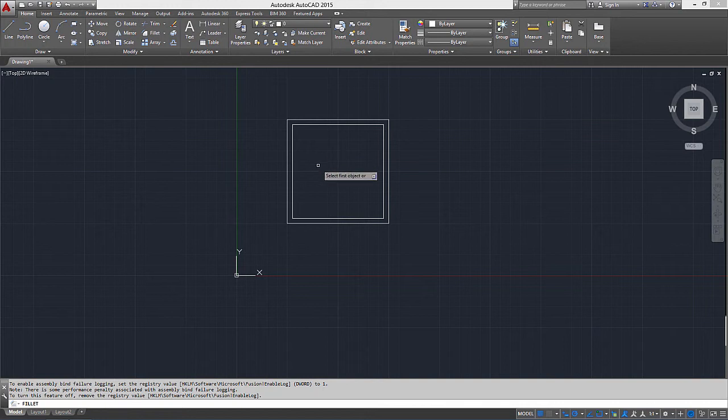So what we need to do is use our down arrow and tap down till we come to radius. So you can keep going around. So you undo polyline, radius, trim, and multiple. So we'll hit radius and then hit enter, and then we need to specify the radius value. And now in this instance it's 10 millimeters. And again, you have to keep hitting enter. And then we can select the first object. Or, now if I wanted just to click one corner and sort that out, I click the 2 lines that make up the corner. And that will round that off.